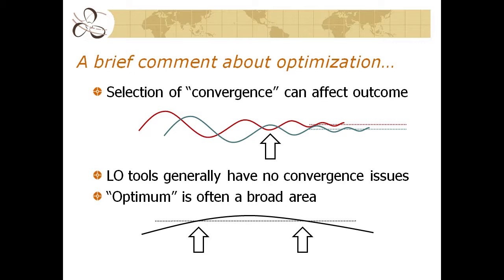Well, if you have different designs in a design space, just take a propeller and you're trying to find the right pitch, and you have this big matrix of different pitch values that you're investigating, you might in fact have the humps and hollows of the convergence that are not in sync with each other, that may be offset a little bit. So depending on your convergence outcome, where if we waited long enough, we'd see that blue was lower than red, if you chose incorrectly and picked a point here, for example, you get an incorrect answer of red being lower than blue. So you'll want to understand the code, you'll want to understand the behavior of the convergence so that you can truly pick out the qualitative relationships of the outcomes.